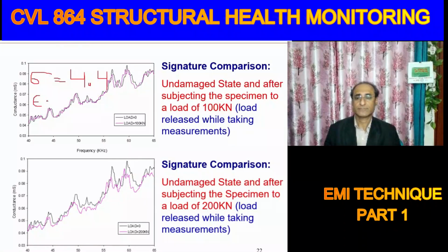Young's modulus will be 25,000 Newton per mm square. And then if we divide the stress by that, that will be the strain. So 0.000017776. And if you want to tell me in microstrains, just multiply it by 10 to the power 6. How much will it come? In microstrains, 177.6.